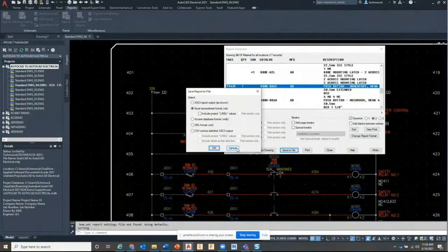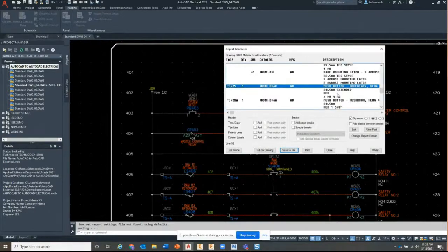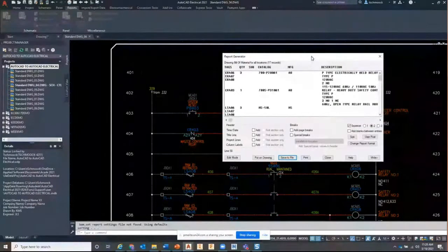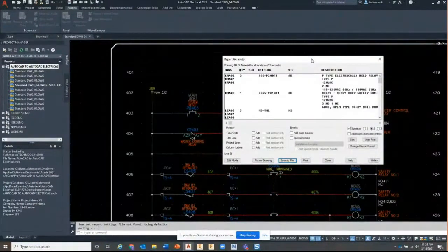I used to put the bill of materials on the drawing, and I reduced revisions down significantly just by exporting to Excel and making the bill of material an A-size sheet extracted right from the drawing, and then adding it to my technical data package. Well, I made a comment about how I could add project lines. Well, here's an option for you.